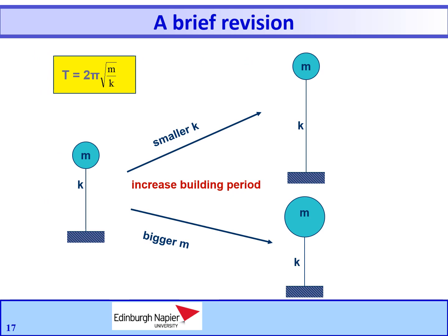The structural dynamics problem can be idealized as a system with a lumped mass and a massless supporting structure. We are interested in understanding the vibration of these structures when subjected to a lateral or horizontal force at the top or horizontal ground motion due to an earthquake. As you can see in this sketch, these simple structures are idealized as a concentrated mass M supported by a massless structure with stiffness K in the lateral direction.